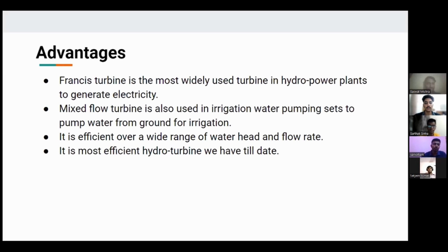So, as we have discussed earlier about the Francis turbine, let's discuss the advantages of the Francis turbine. The first advantage is that no head failure occurs even at low discharge of water, and variation in the operating head can be more simply controlled. The mechanical efficiency of the Pelton wheel turbine decreases faster than the Francis turbine.